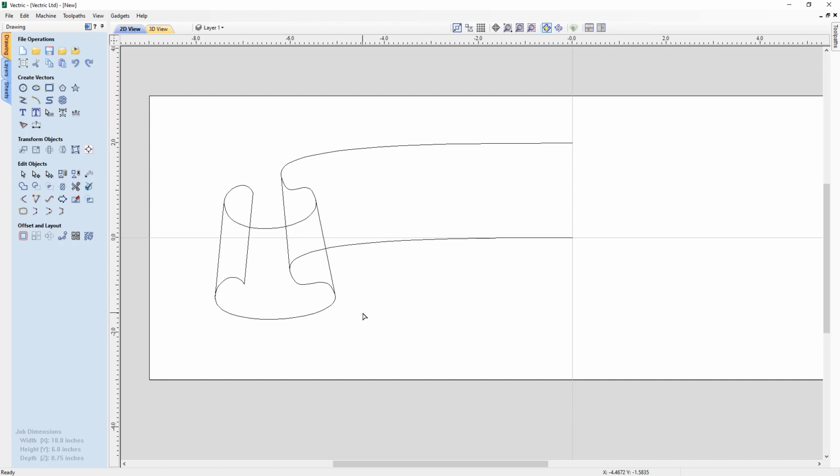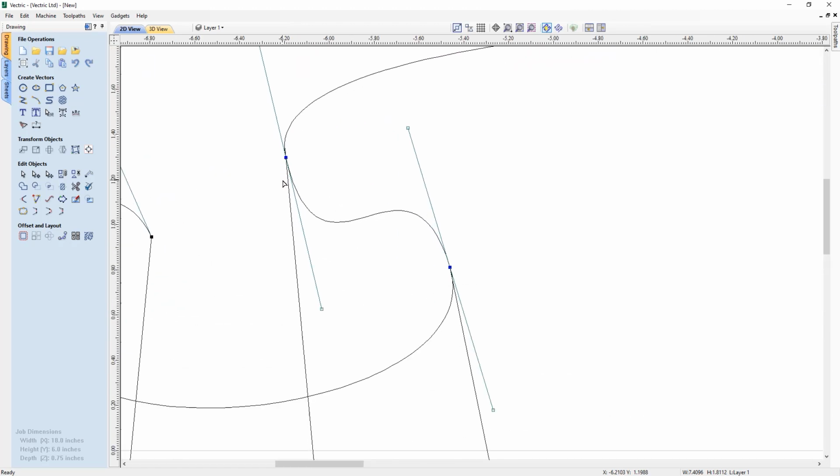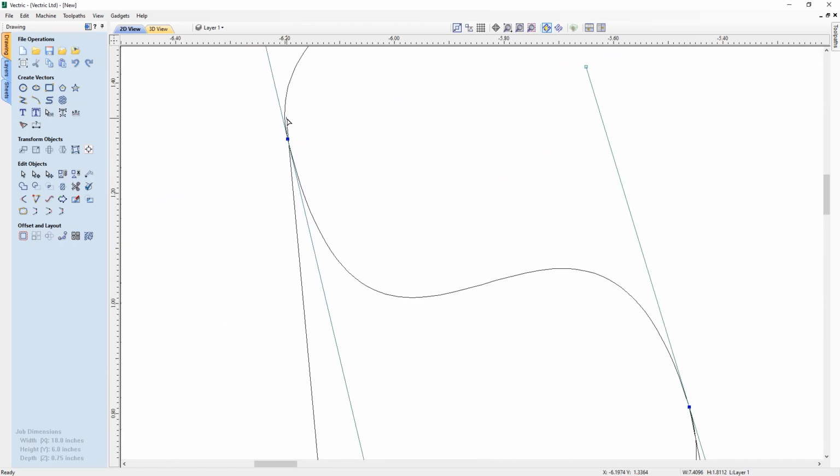So now what we're going to need is to actually cut these two long lines that we made into the parts that we need to create some cookie cutters that we're going to use to cut out some areas of shapes that we're going to create using our two-rail sweep when we go to create the 3D model of this. So to do that, we're just going to kind of note in our head where these lines kind of connect, and we're going to go ahead and choose this, and I'm going to zoom in and I'm going to cut that where it kind of intersects.